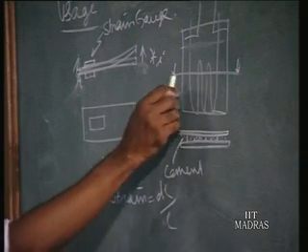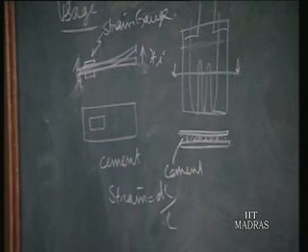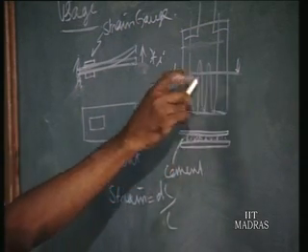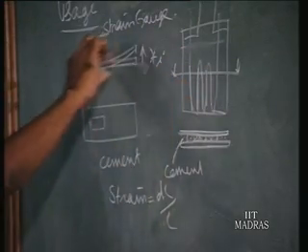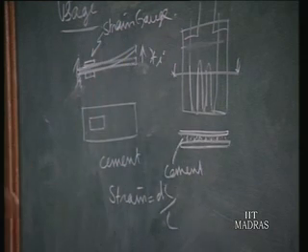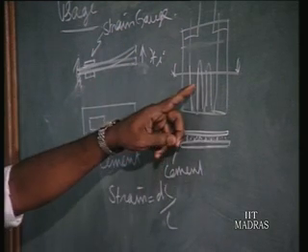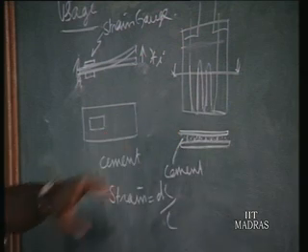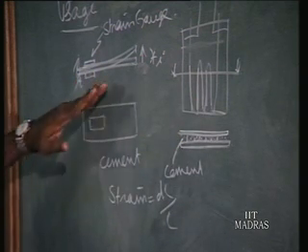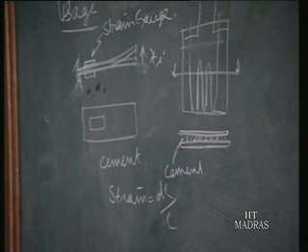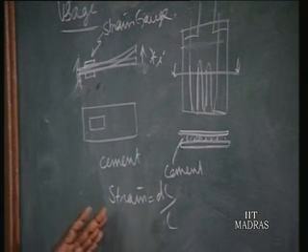In such cases, it is sufficient if you paste the strain gauge with its axial length along the axis of the cantilever, in the same direction as the strain. Suppose in some structures you will find the direction of the strain will not be known. For example, in rocket panel structures, due to acoustic stress or strain, the panel is strained in all directions. So we find no fixed direction can be fixed.